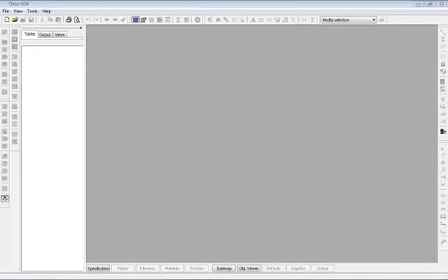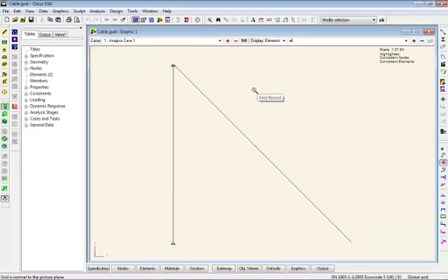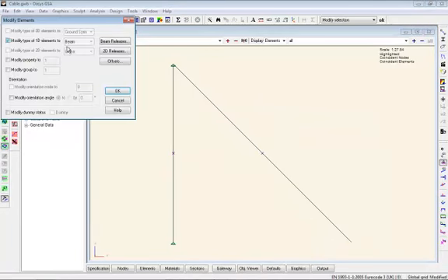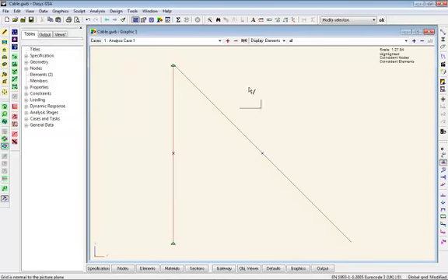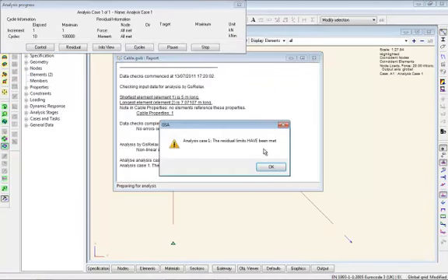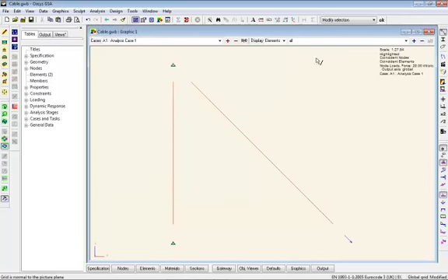We also have a model here to show cables. If I just change these two cables back to ties, you can see we have a point load here, a tie to a support point, and another tie, another support point. And if we run the nonlinear analysis on this, you see the end result is an axial load there.